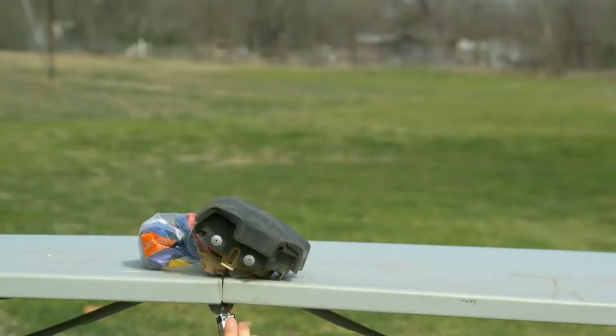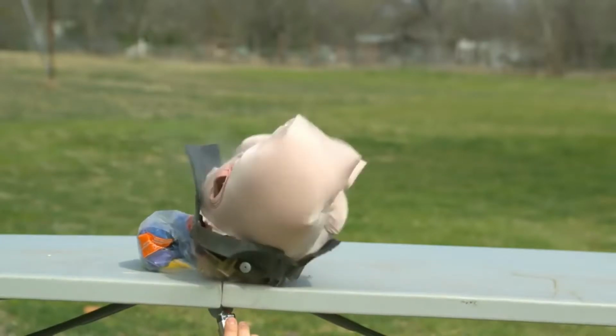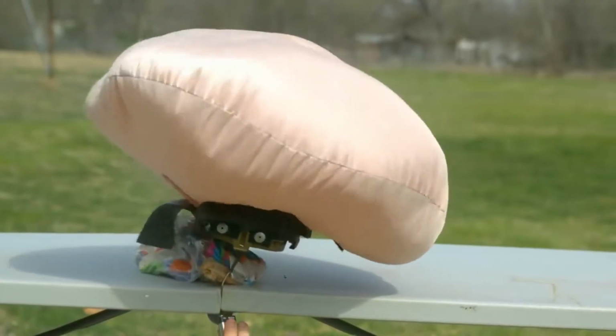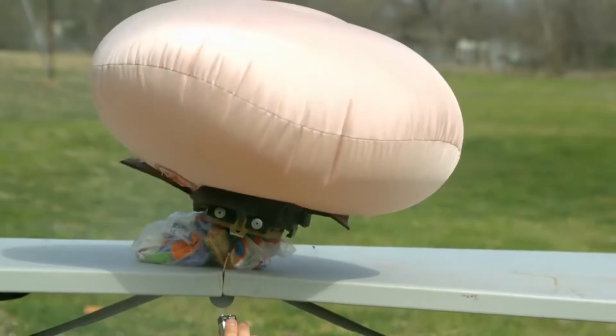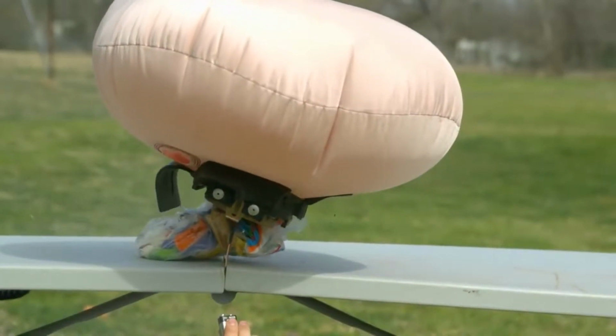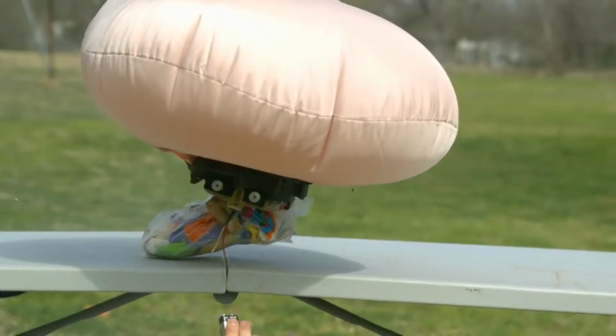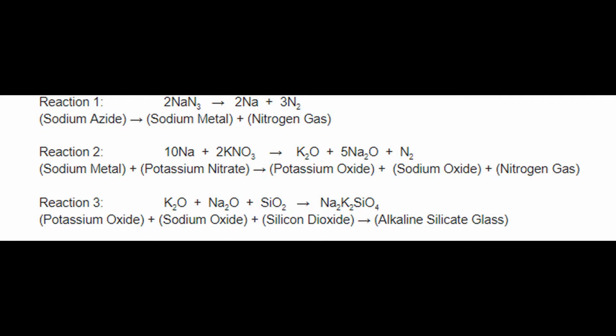Airbag activation is approximately 40 milliseconds. To fill the airbag as fast as possible, a lot of nitrogen gas needs to be produced. Therefore, at first, sodium azide has to be decomposed into sodium metal and nitrogen gas, which is the first reaction.